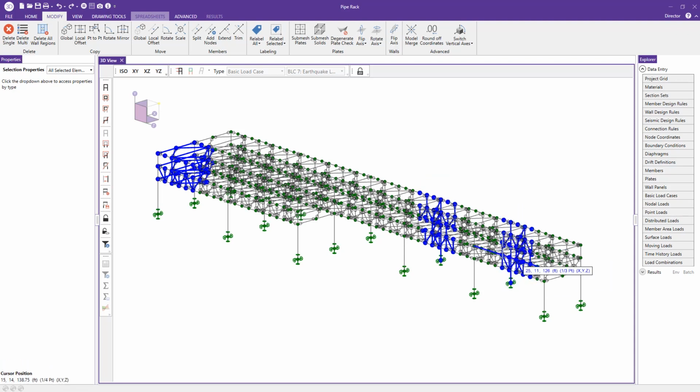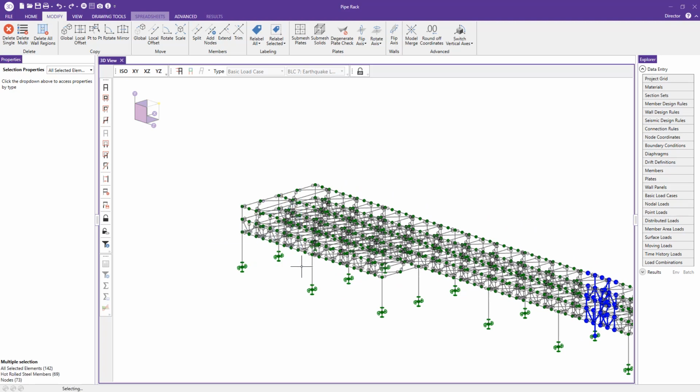This makes it easy to do different selections across my model. And if I want to unselect a group, I just hold Shift and click, and now you see a minus sign. So if I box that, it's going to unselect that information, and I can do that for this group of elements as well.